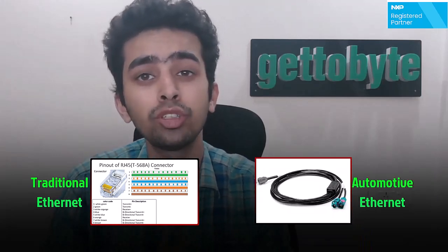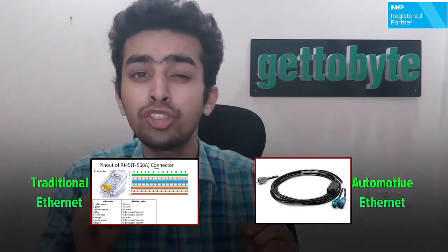Reduced wiring complexity. Unlike traditional Ethernet, which uses 10 to 12 pins, automotive Ethernet uses a single twisted pair cable, significantly reducing the vehicle's wiring harness complexity, weight, and cost. And it's an industry standard, widely accepted, enabling interoperability across automotive manufacturers and suppliers. Automotive Ethernet is not just theoretical; it's already driving innovation in the automotive industry.